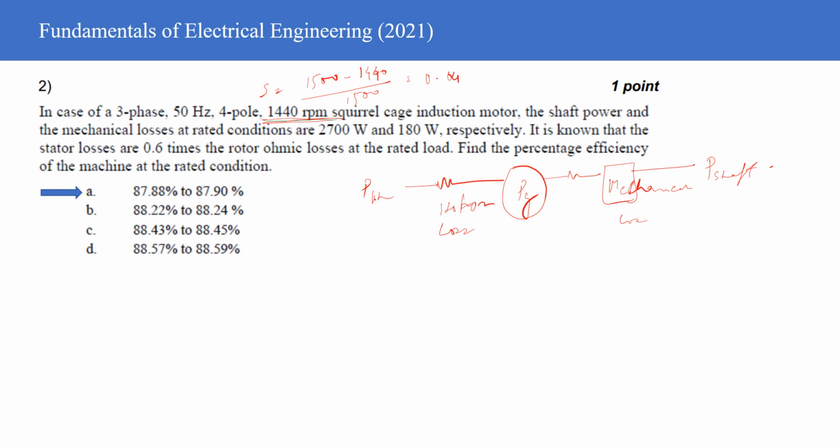So shaft power is nothing but the power which is actually being utilized to drive a particular thing. So if you fall back, this is the input power which is given from the electric supply unit. You give some power, you will have some stator losses. The stator losses are copper losses plus core losses. After that you will get some air gap power. You subtract the ohmic losses, again the copper losses of the rotor, plus a very small amount of core loss in the rotor. So this is the rotor copper loss plus core loss. After that you will have some mechanical losses, which are friction and windage loss, and other losses associated with the slip. And then finally you will end up with the shaft power, which you are using for driving the application. So this is how the power flow diagram is for a regular induction machine.